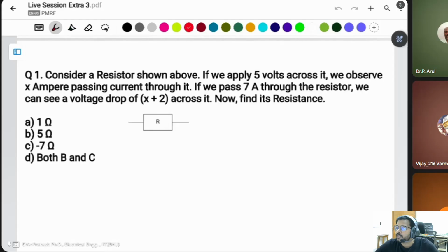And what is the average maximum power absorbed by ZL? Questions 6 and 8 are approximately the same. Simply you have to find the Thevenin equivalent impedance and compare to R plus jXL. That means ZL is equal to ZS conjugate, which I only taught in the previous session.